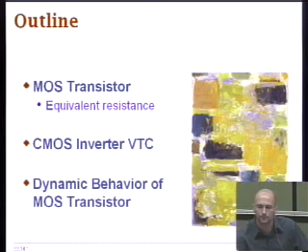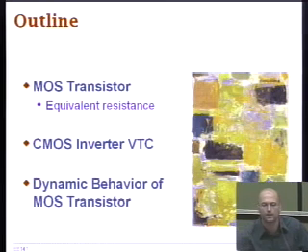You said capacitance was the main reason we use short channel devices, but long channel devices have a higher current, which would charge the capacitors and discharge them faster, correct? That's right. But we will come to that probably next class. You will see that in the product of equivalent resistance and the capacitance, the long channel is less favorable because the capacitance and resistance will be higher in the long channel.